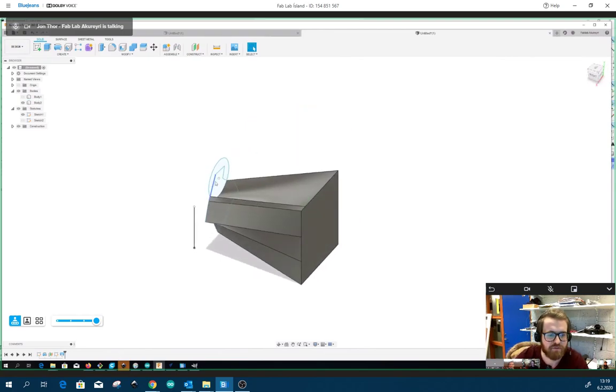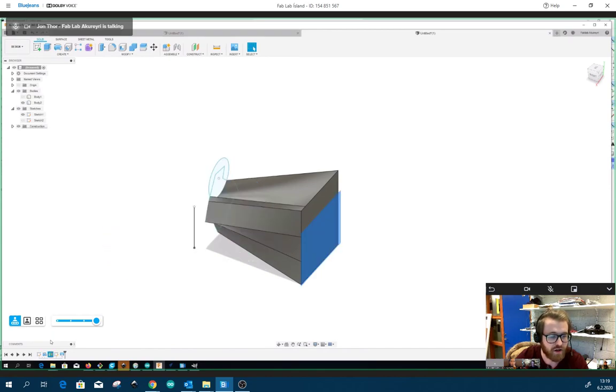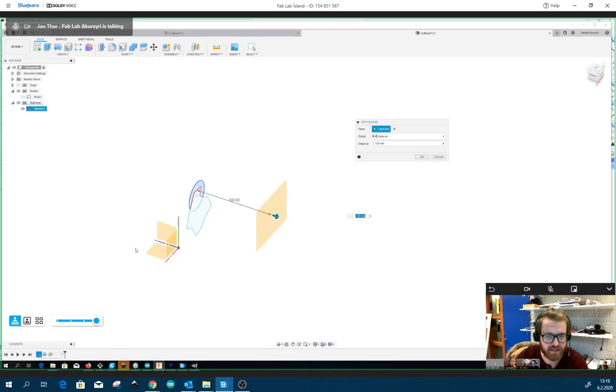As before, we still have the option of the timeline. We can see all the objects and all the actions we've done. So this was my first sketch, then we revolved it, I hit the revolve, and then I offset it and made a new loft. I can take this offset plane that I made, double click it and say, no, this is supposed to be much bigger, -200.